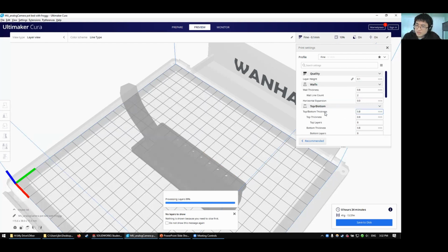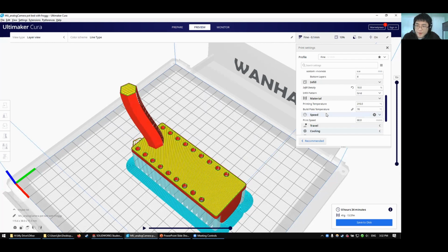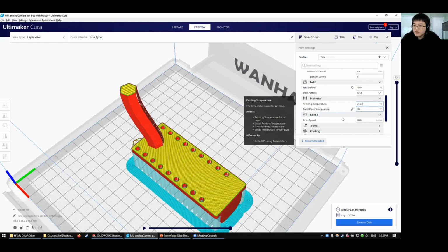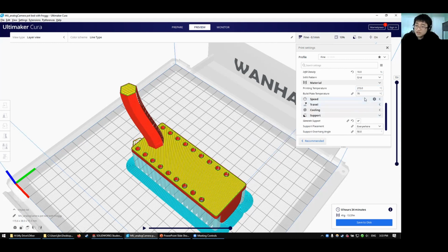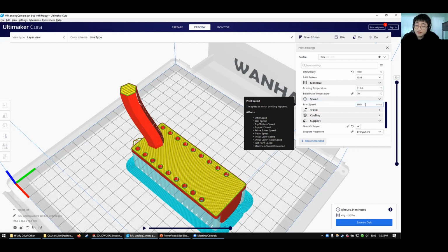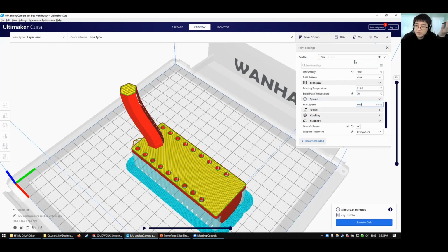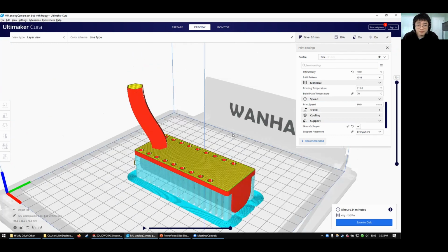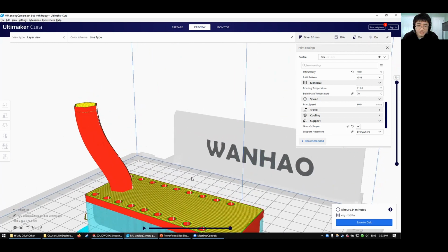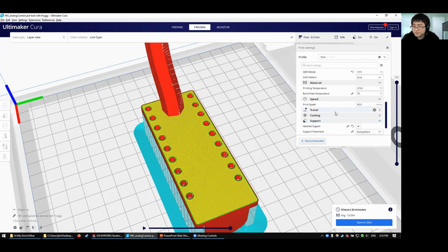Once you do select these options for your printer, you will probably, after a couple different times of printing, find out, oh, hey, I usually should set a little bit higher temperature than the manufacturer specifies or something. Or maybe you tend to go a little bit slower on the prints because it tends to be better quality. Then you can set that as a preset and then just share that with your team and use a single preset for all your prints pretty much. So that's usually a pretty good idea. I don't know if I have the preset for robotics here. I think I might have. It's been a while since I printed it. Well, that's usually something good to do. Save a preset of your usual settings.